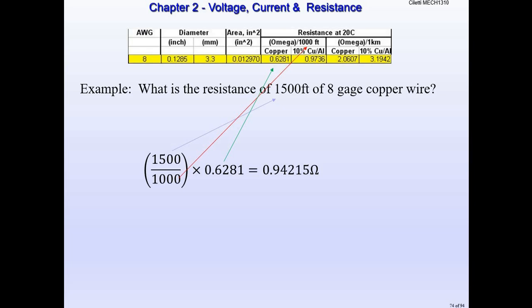Okay, so that's going farther than 1,000 feet. We're not going to have very much resistance, so that's good. And this is why you want a higher gauge wire. So when you buy an extension cord for your saw at your house, that's why you want a better extension cord. You don't want the little scrawny things. You're going to blow it up because you're going to want to run at full amps. You want to run 12 amps on your saw so you can cut through your wood. You don't want it dying down because you can only pull 5 amps through that scrawny little wire.